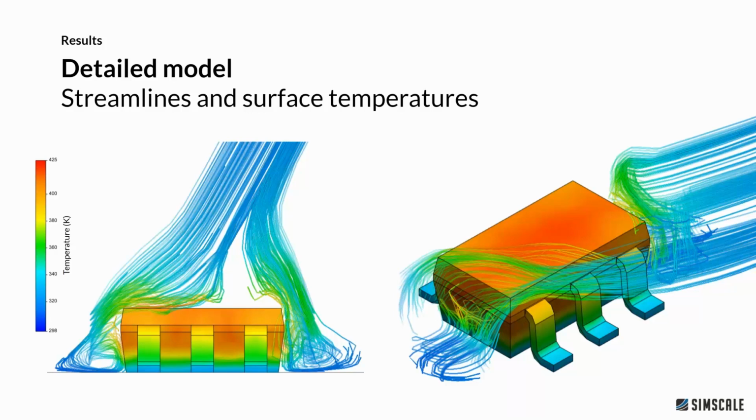But it's important to remember what is important to you when you're doing the CFD analysis. So if junction temperature is the important thing for you, then use a resistance network. It's going to reduce your costs. It's going to increase the stability of your simulations. It's going to increase the robustness. And at the end of the day, that should be all we're interested in: drawing a line somewhere to get accurate results.